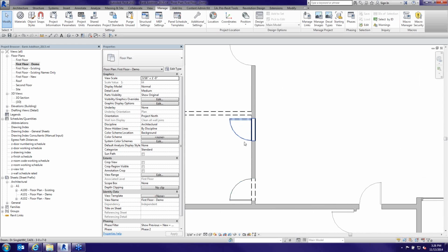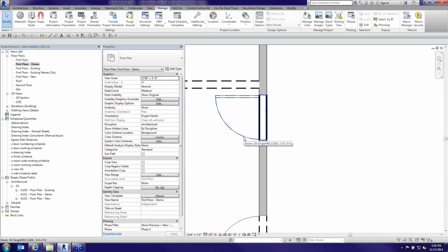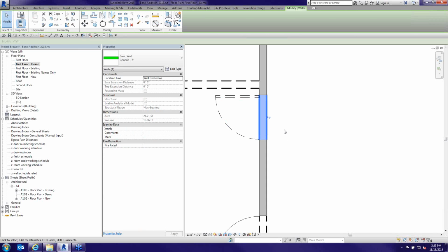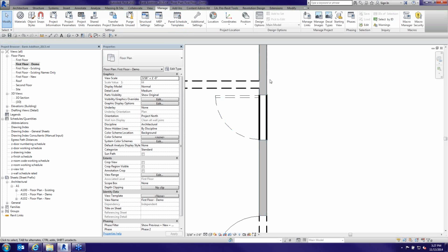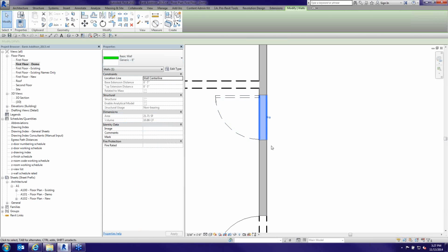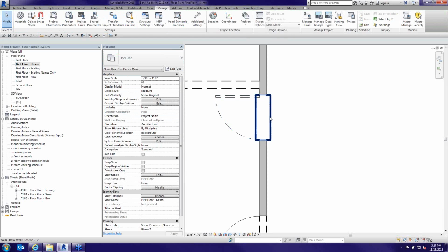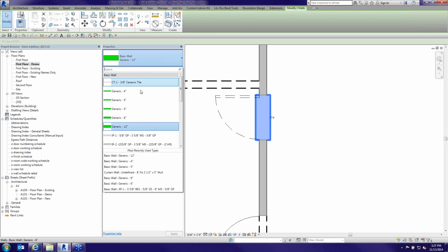So we start looking at objects. Revit, when there's an object being placed into an existing, so if I put a door, a window, a curtain wall inside of an existing, Revit's going to automatically come and do what's called an infill panel, and it's going to say, hey, this was a basic wall. I'm going to infill that with a new wall. You will notice that on infill objects, there is no phase created or phase demolished property because it's being infilled to the existing wall. I can tab and select it and change it to be something else. I can change that to be a different wall, but there is not a phase option.